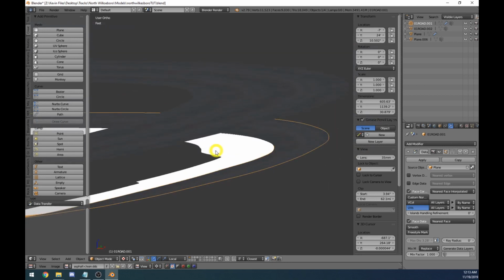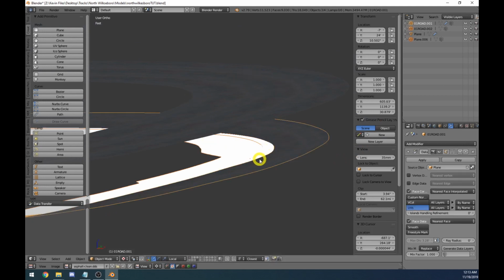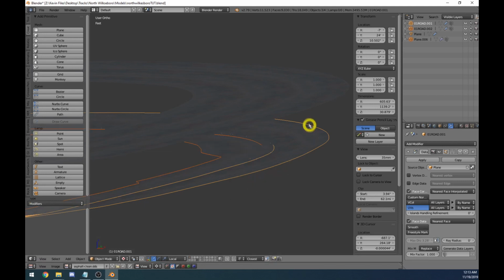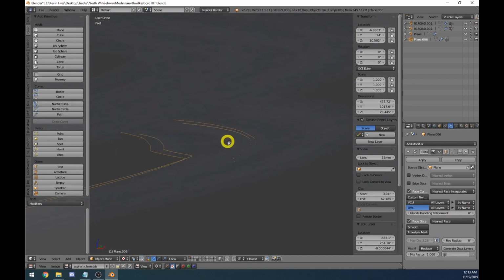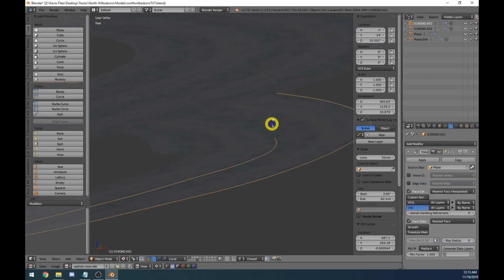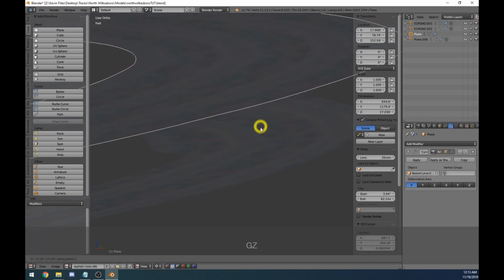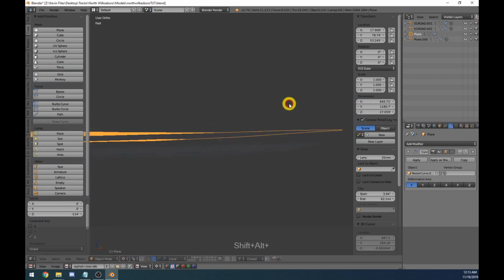So now what we want to do is send this same UV map just as a base to all those other objects. So similar to what we did with the multi-user objects, but we're going to link modifiers. So Control L, and we're going to do modifiers, and that's going to send this same modifier over to all the other objects. So now this is the same as this to a degree, but see it's up here elevated. As I move it down, you see it should move the UV a little bit depending on.